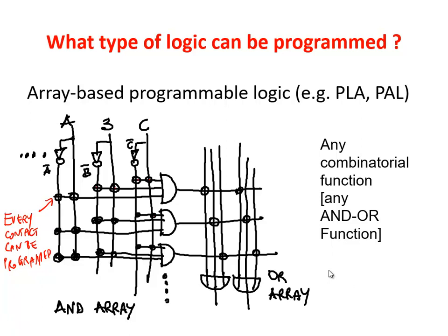So, you see what the situation is. Basically, you have a 3-input AND, and the inputs are connected to C and not C, B and not B, A and not A. So what you can do is specify the AND plane by opening or closing those contacts. Okay?